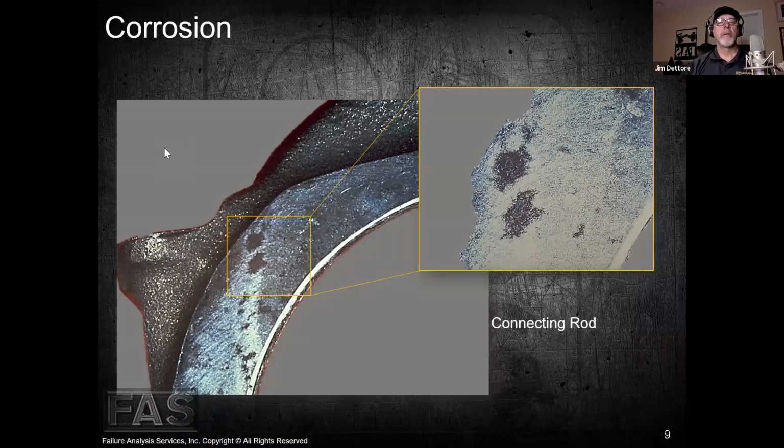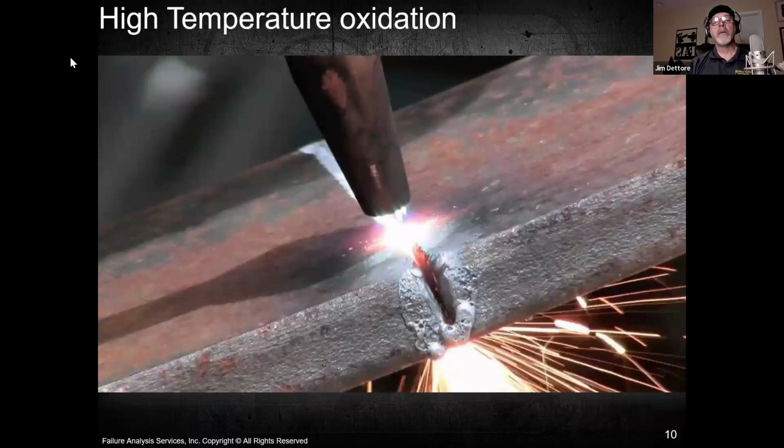So, all right. The last type that I thought we'd discuss, Michael, is high temperature oxidation corrosion. And I guess a relatively easy way to explain it is the cutting torch. So if we're using an oxy fuel torch, we have some type of fuel, such as propane or acetylene, and then on our cutting head we have the lever that we push down, which is the oxidizer bar. So if we just take that torch tip and put it right against the steel without preheating it and hit that oxidizer bar, it essentially does nothing, right? Wastes a little bit of time and oxygen.